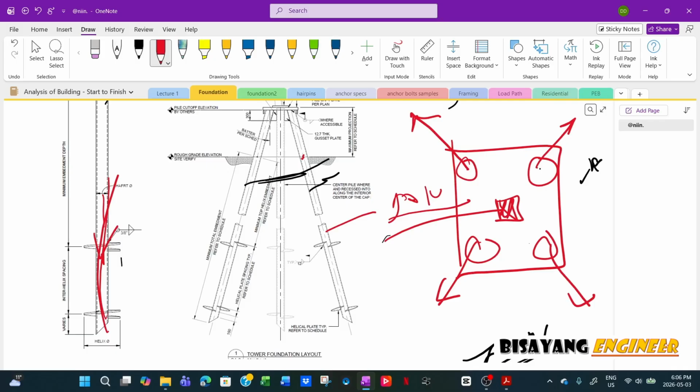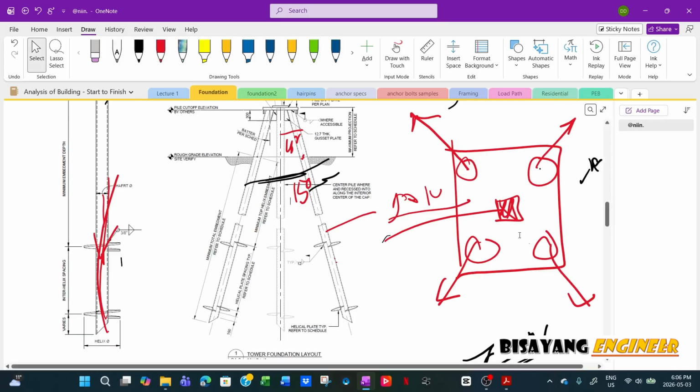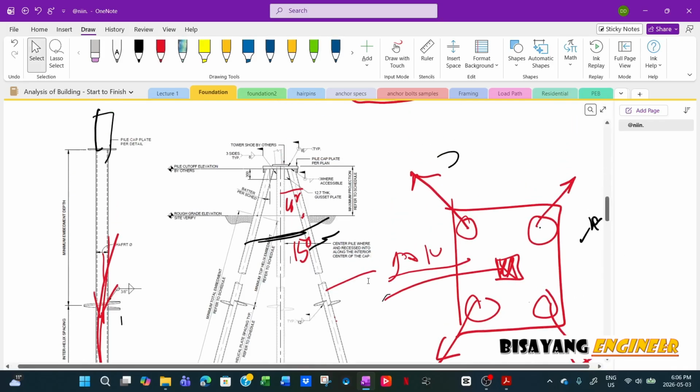So that's why you are seeing this one here, and then at the batter, usually sometimes 10 degrees or 15 degrees, but you can install that up to, usually in my experience, we battered that one at most 45 degrees. So yeah, that's screw pile or helical pile.